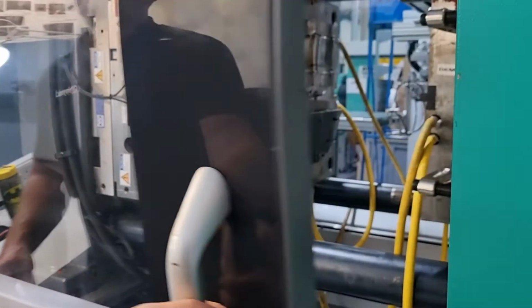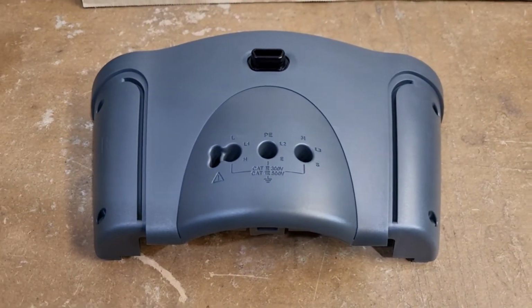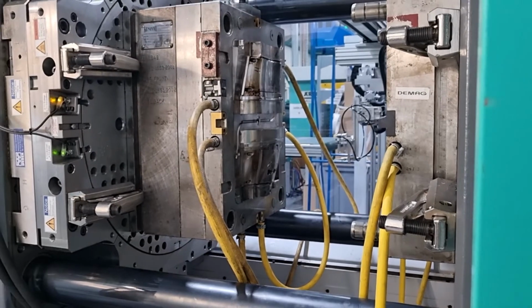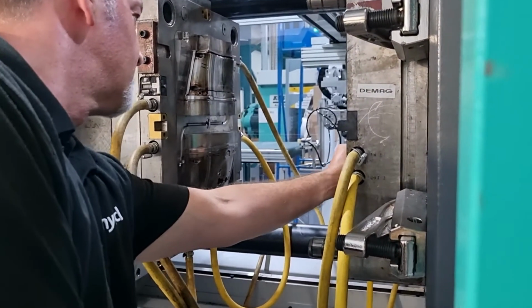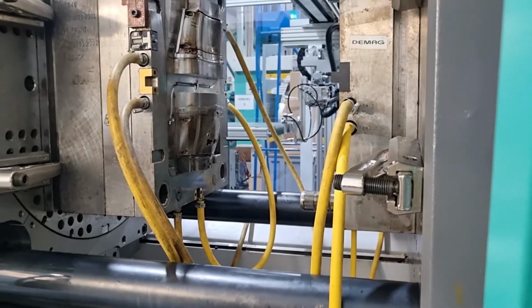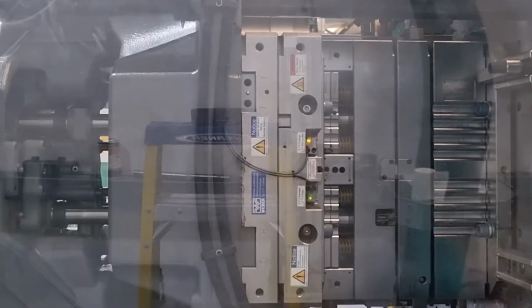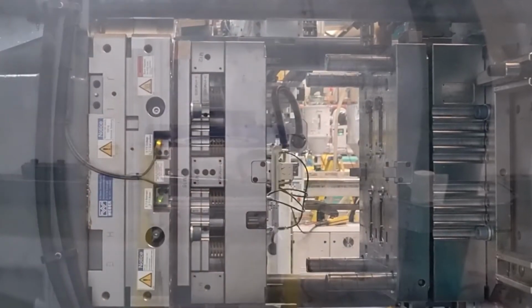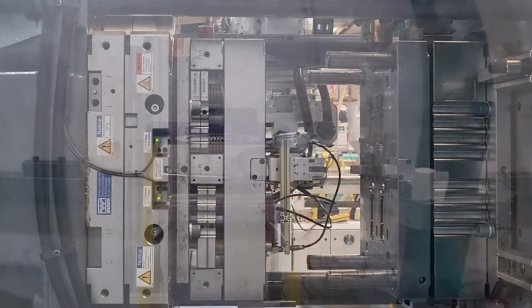With hot runner systems, like this tool which produces the front case for an electronics enclosure, the molten polymer passes through a similar style of runner system to a cold runner. However, the biggest difference is that when the polymer gets to the runner tip, it's reheated before passing through the gates and into the mould core and cavity. This means that any polymer left in the runner system remains molten, ready for the next injection, and does not have to be removed along with the part.